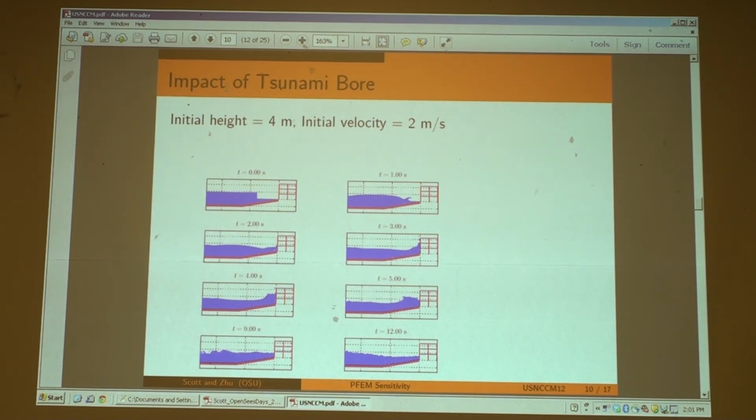Yep. In the fluid domain, does it give rise to non-linearity in the equation due mainly to the change of geometry? Or is the material implicitly linear elastic? It's a linear fluid, but it's a non-linear solution because the mesh is changing, and there's turbulence, and the solution strategy requires that you iterate to solve first for the velocities and then go back and do the pressures. So there's some iteration required.